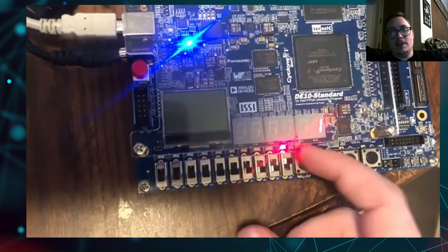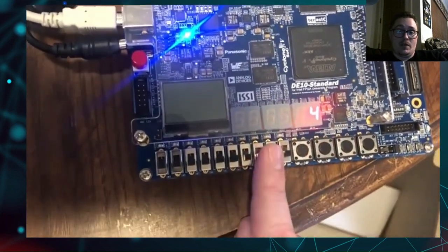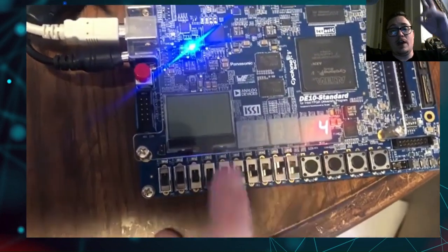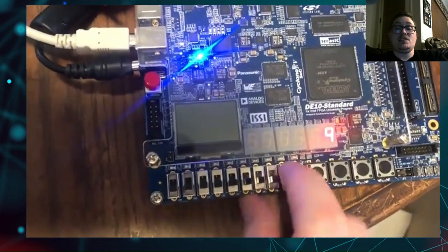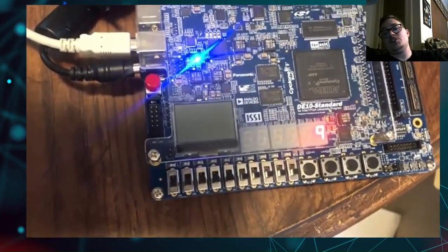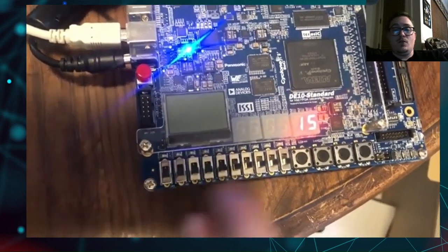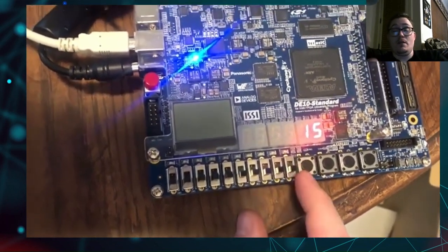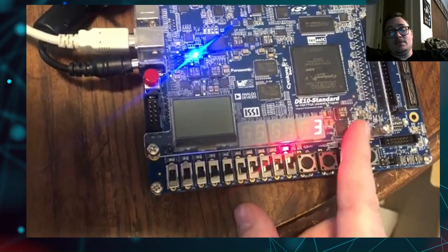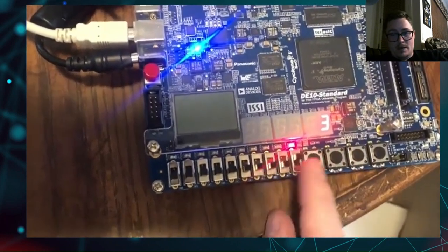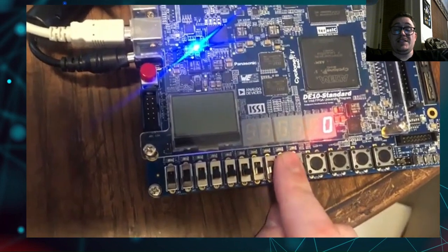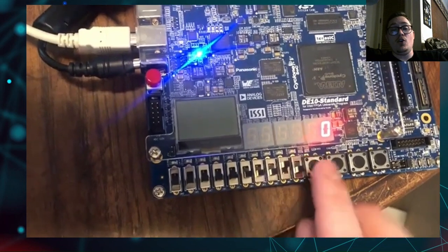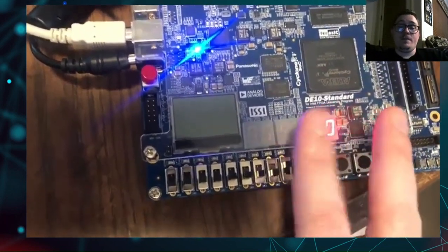operation is addition. But as I flipped it high, we saw that it was subtracting, 5 from 4 being 1, and that second switch went high for us to AND those two values. And obviously 5 and 4 share that 1 in the 4's place, and so that's why we see 4 as the output. Now, if we were to enter, say, 6 and 9, we would see 15, which is actually the greatest number we can display on the two hex displays, because that's the largest 4-bit number, and we would see the same results. 9 minus 6 is 3, and then if we were to AND those, we would actually see 0, because none of the values in the binary value of 6 or 9 are shared, and because there are no ones that are shared, we see only 0.